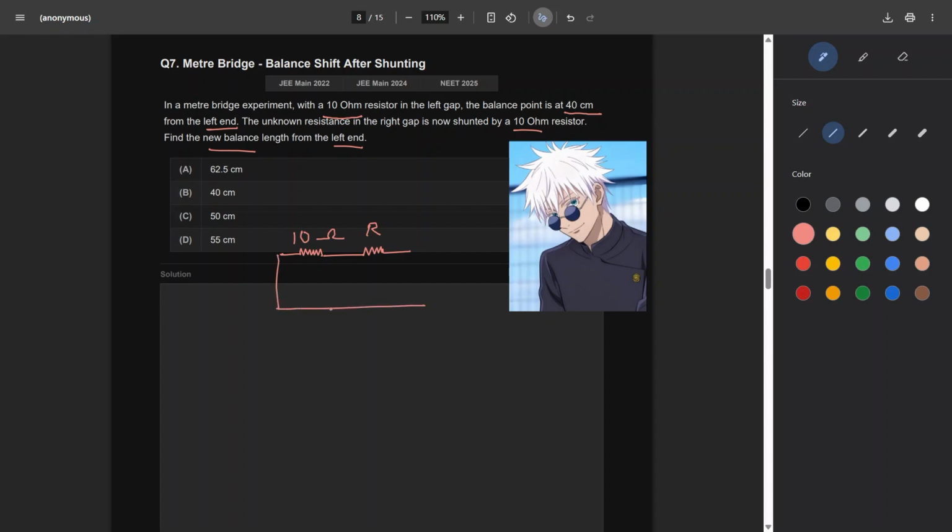We just know this is the meter bridge, right? And we have the jockey at 40, right? So this will be 60, right? Whenever you have meter bridge questions, just take the resistance as 1 ohm per centimeter. This 100 centimeter, as you know.